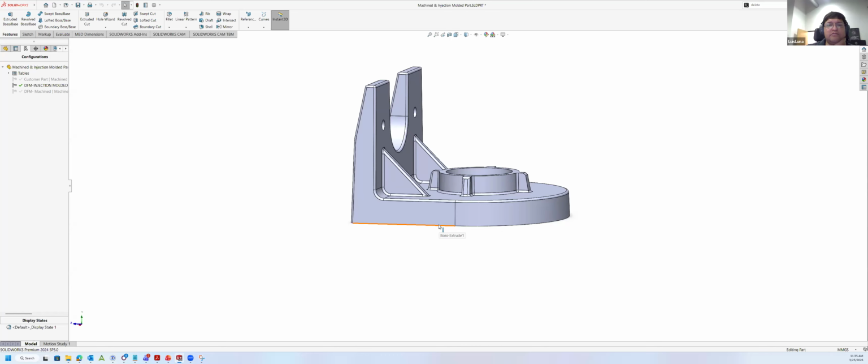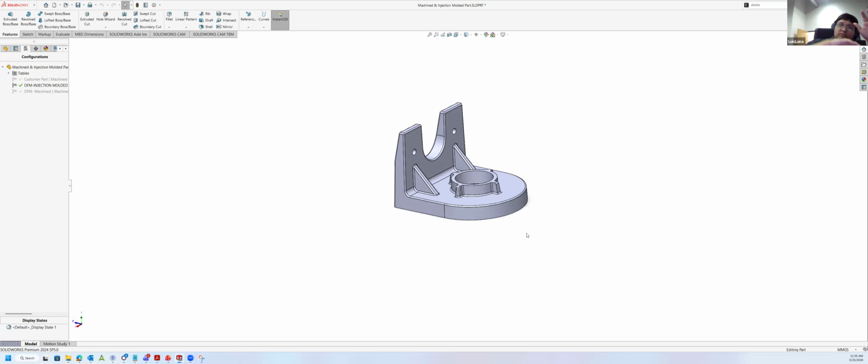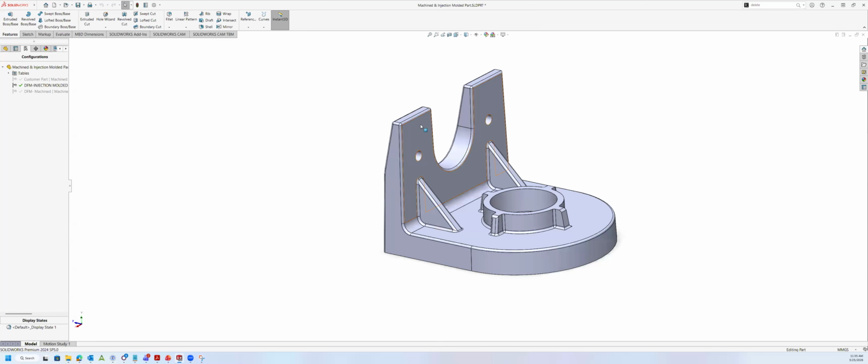Was there an advantage to the bottom being kind of embossed like that for the mounted feature as opposed to doing just a shell negative from the bottom? When I pictured the other part being injection molded, I figured it would be more of a shell from the bottom and it would just be one thickness all around. Is it the cores that are preventing that on the left side? So when you show this part, what will happen is you'll have some thicker areas when it comes to these side core areas.